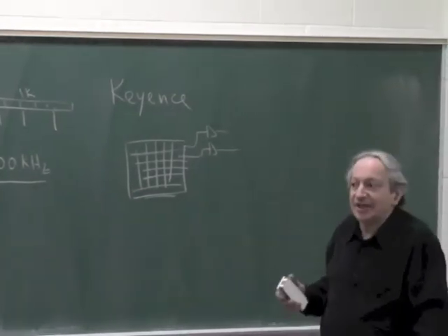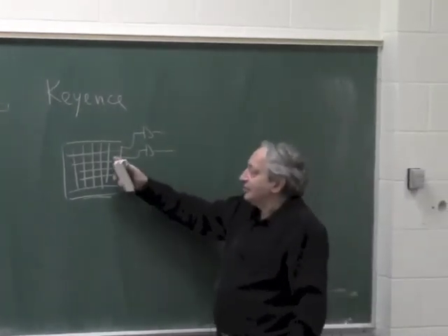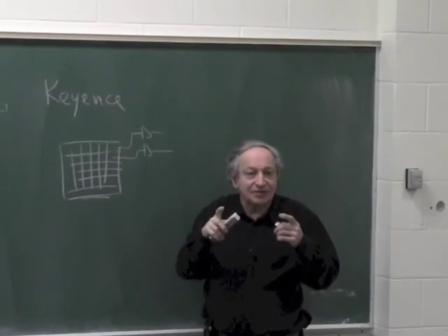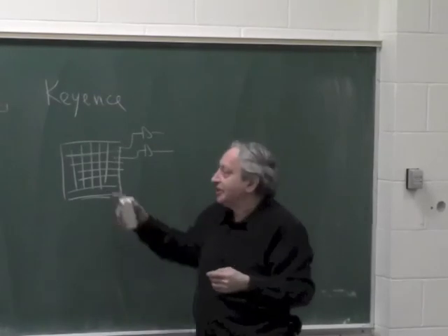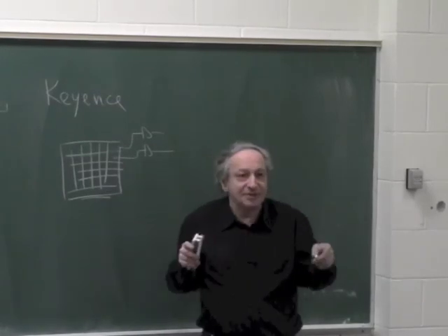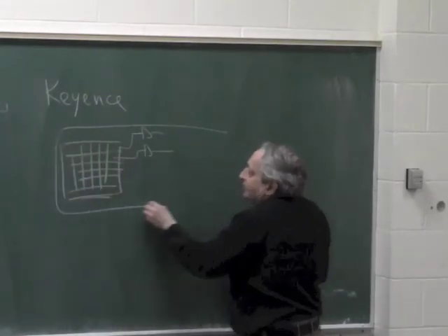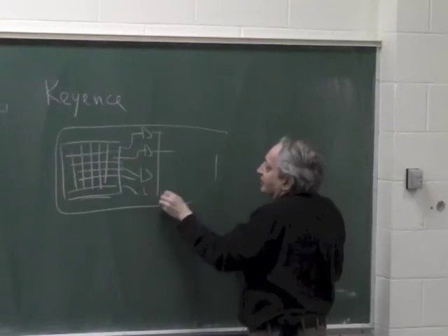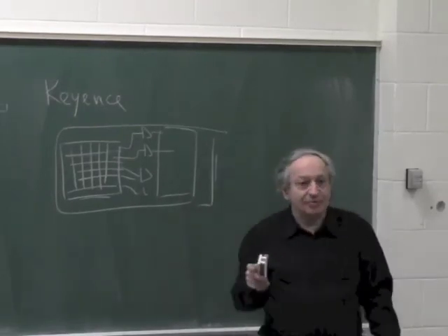And then you can make an array processor connected to a camera in which each pixel is brought out. Because in the silicon, 10,000 wires are not a problem. If you had to bring it out with a connector with 10,000 pins, it wouldn't work. But if it's all one silicon chip, and these are brought out on the chip to the amplifiers, and then you have an array processor, all on one chip, that's very doable.